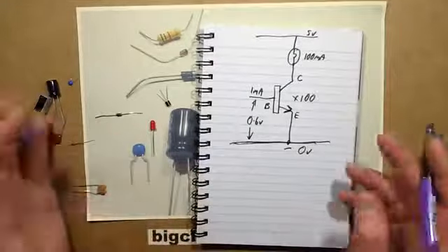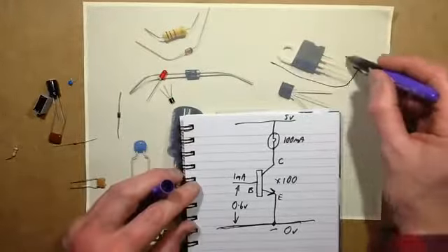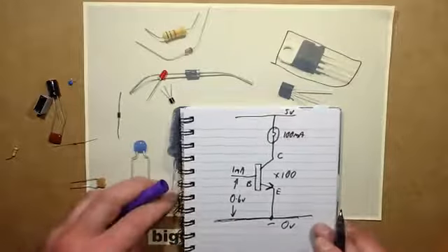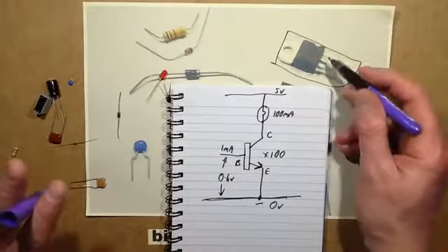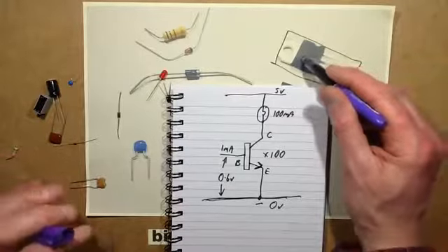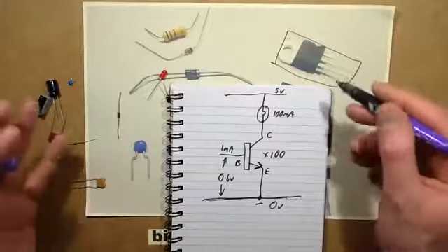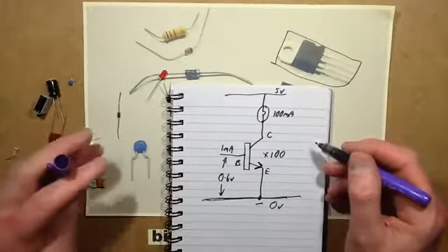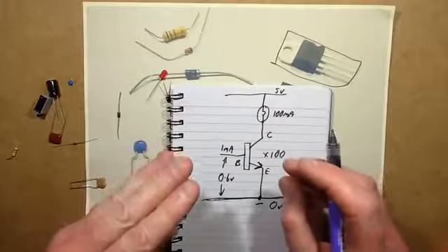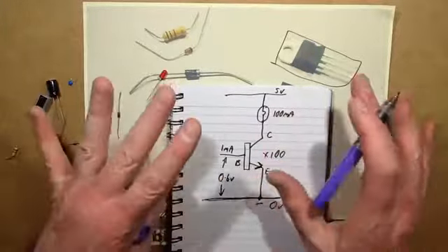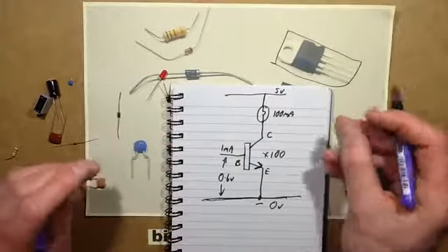Other types of transistors, like the one pictured here, are MOSFETs, and they're optimized for switching really high loads. I chose the STP36NF06L for my RGB controllers because it can handle a lot of current, and its on-state resistance is so low it doesn't impede the flow of current when turned on, so it doesn't get very warm.